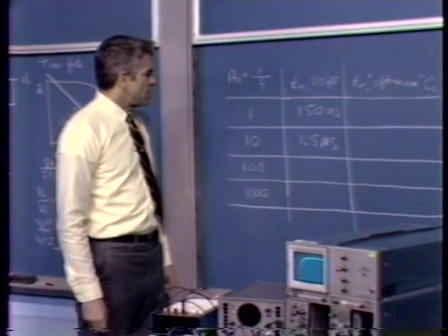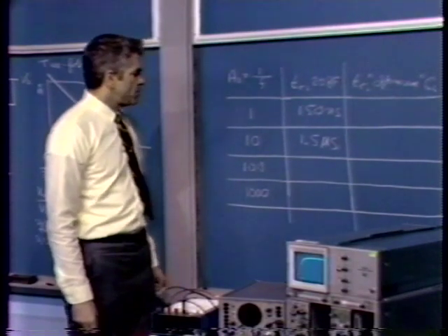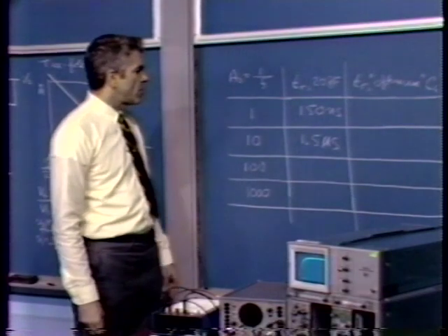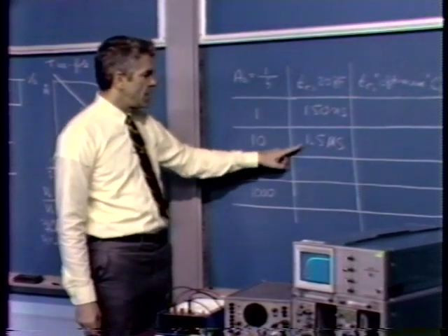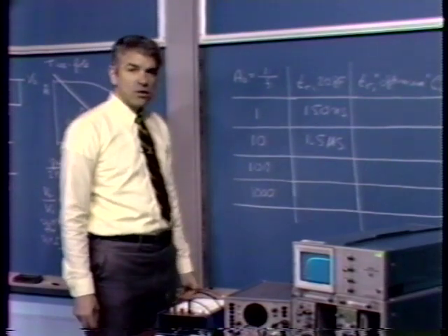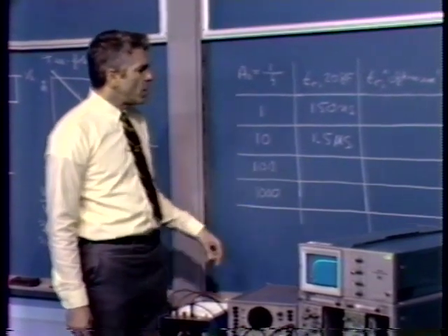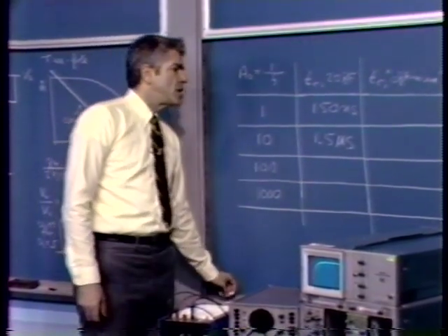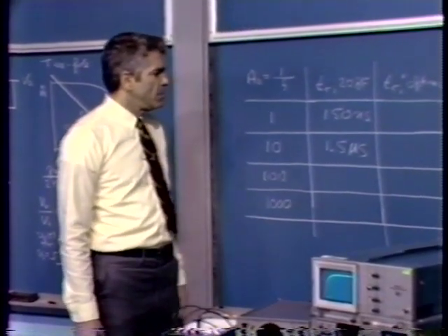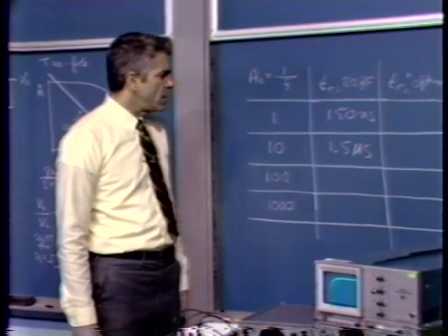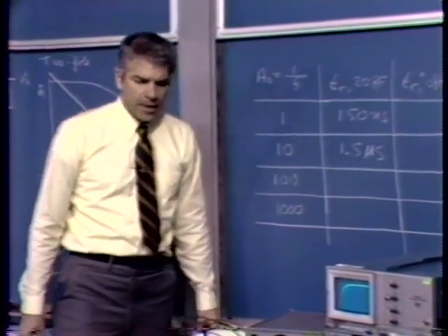We found out that the time constant associated with the closed loop gain was proportional to the ratio C sub C over F. Here we've kept C sub C fixed. We've changed F by a factor of a tenth. We'd anticipate that the closed loop response would slow by just about that factor of 10, and in fact it does. We also notice a little change in the character of the response. The original response, this one, had just a little bit of overshoot. Once we are observing this response, we noticed it looked very, very much first order.